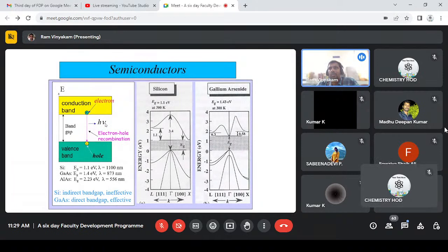It creates a bubble in the bottle, and if you move the bottle upside down, the bubble will move. But what actually happens is the water is moving, and the air bubble seems to be moving fast. The same applies to hole movement, where the hopping mechanism of electrons in the valence band leads to hole movement.